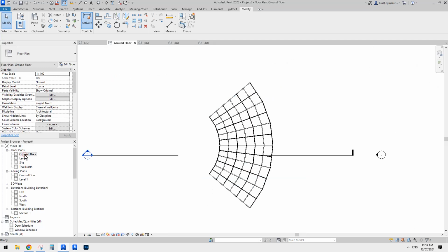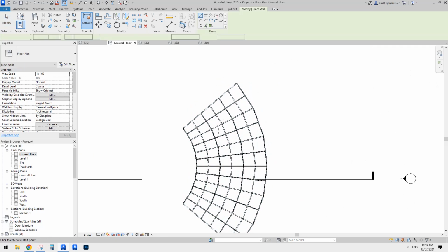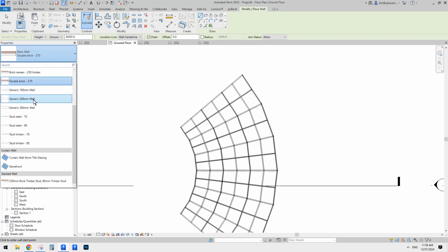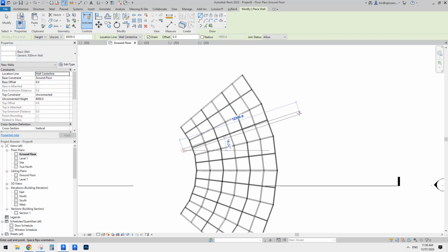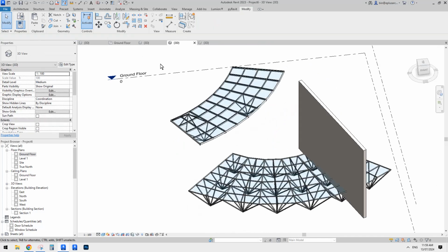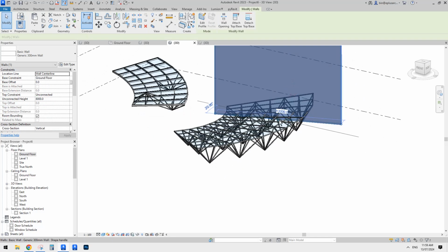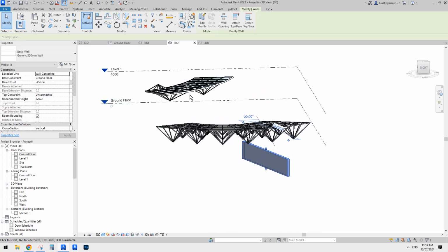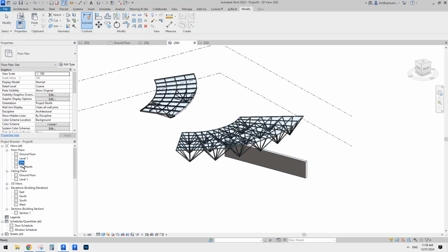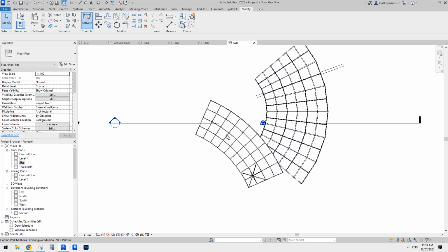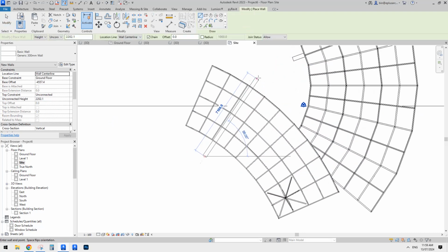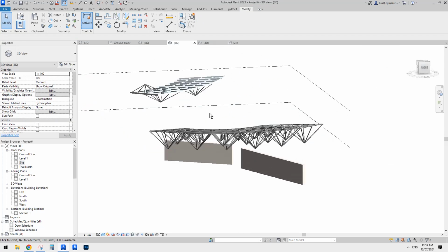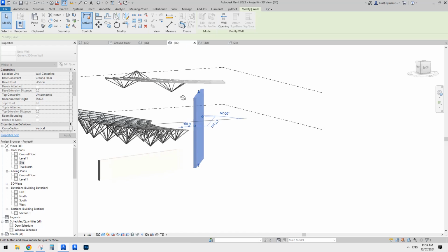Let me do one last thing. I'll just maybe do a wall. Let me think. Just do a basic wall under this grid. Okay, and then go to 3D view. Oh, that's too high. Let's just make it lower. So, hang on, I should do it over there. Let's go to site plan. Sorry about that. So maybe a wall here. I'll CS, create similar, and just do a wall underneath this grid, and go to 3D view. Maybe go up a little bit.